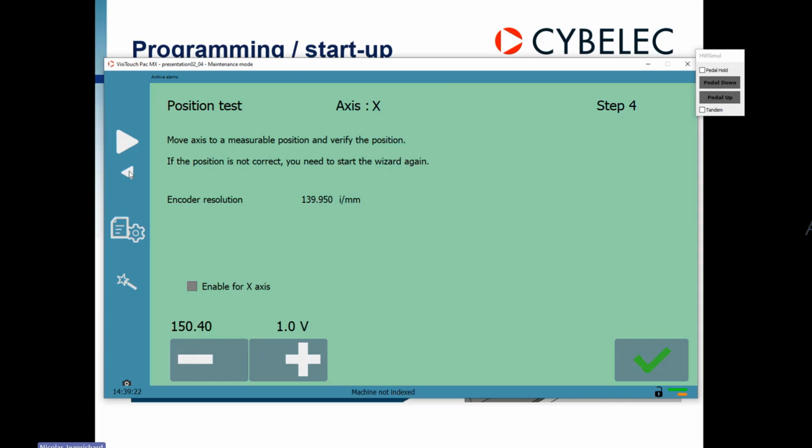So we go back here and we measure again min, max, and we let the controller calculate. Maybe it's also that we have an issue with the encoder feedback and we miss some impulse or something like that. It could be also a hardware issue as well. The goal of this page is to simply test and to confirm the resolution is correct. Once this is done, we can go to the next page.